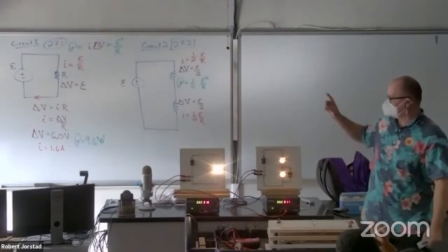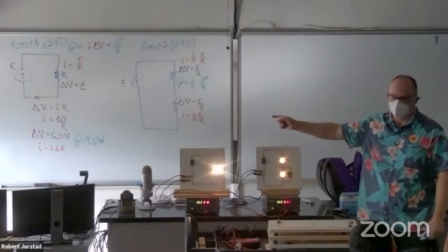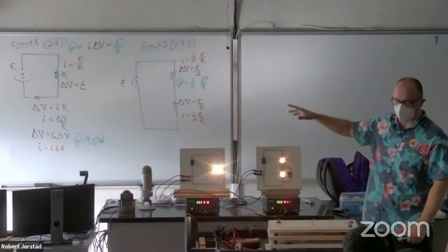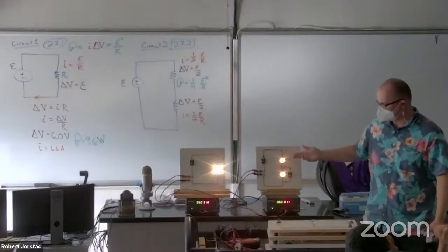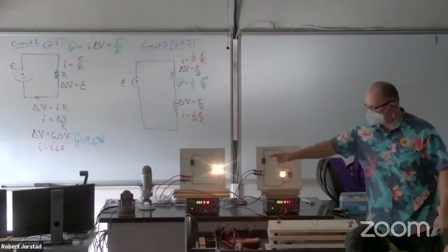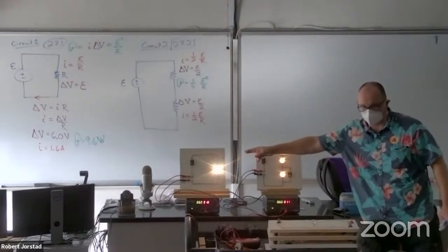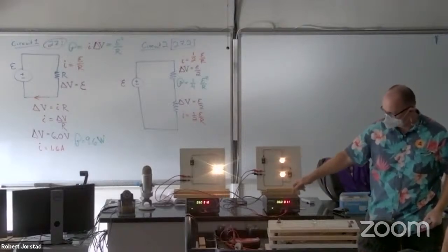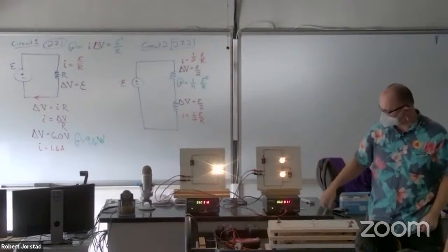Remember that the math we do for theoretical circuits almost never matches reality exactly. It gives you a ballpark figure. Here, with these particular light bulbs, this one must be a whole bunch warmer, and the resistance is significantly higher, because we would actually expect 2.2 on that one, or only 0.8 on this one, however you want to look at it.